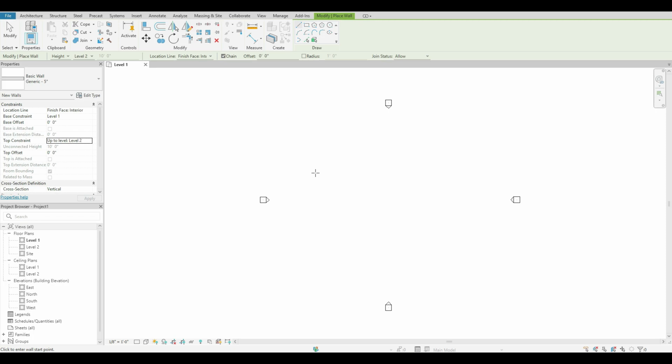So what you are going to see me do right now is make my first click. Once I do that, you will see that my wall now appears within my model space. You will also see that it is not moving from that first click that I selected, right? So now that we have it anchored within our space, we want to choose, well, what direction do I want to take that wall in? Am I going 90 degrees up perpendicular? Am I going horizontally across?